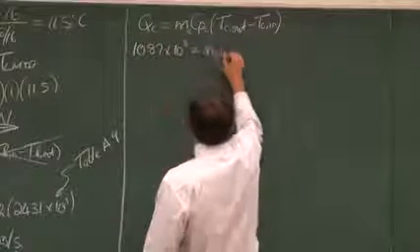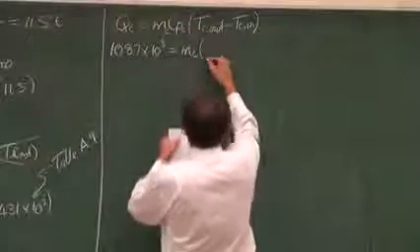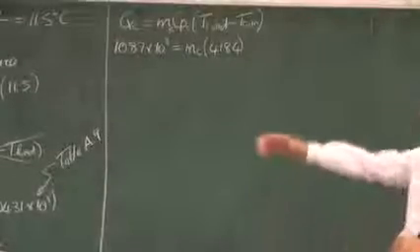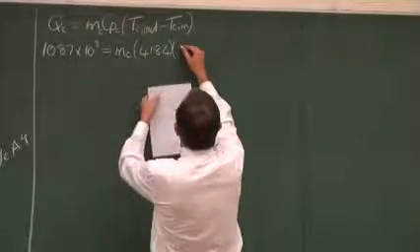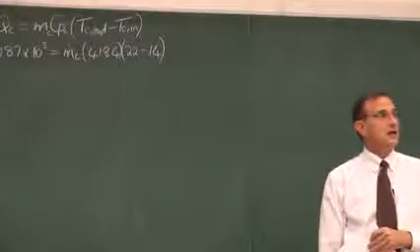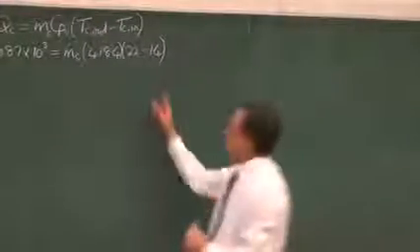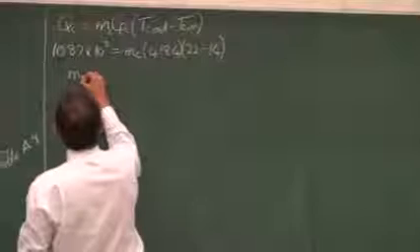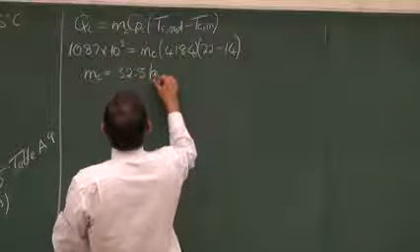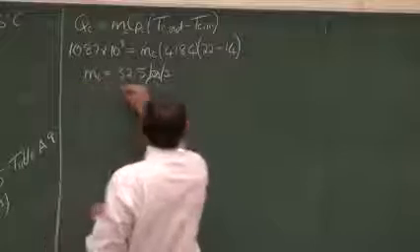It's equal to the mass flow rate on the cold side multiplied by Cp of water, typically between temperatures of 22 and 14, it would be 4184, multiplied by the outlet temperature, which is 22, minus the inlet temperature, which is 14. So it is very simple to calculate the mass flow rate of the water as 32.5 kilograms per second.